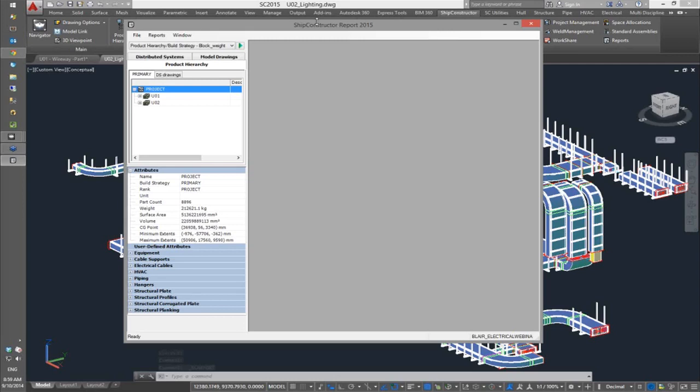The cable report is also the means of generating the cable schedule. So we support two styles: what we call the vertical style, which is essentially one page per cable, and then more of a spreadsheet style, which is just the cables listed vertically down the sheet, with the actual list of legs that the cable goes through in one particular column on the side of that report. So let's see if we can give you a quick example of the two.